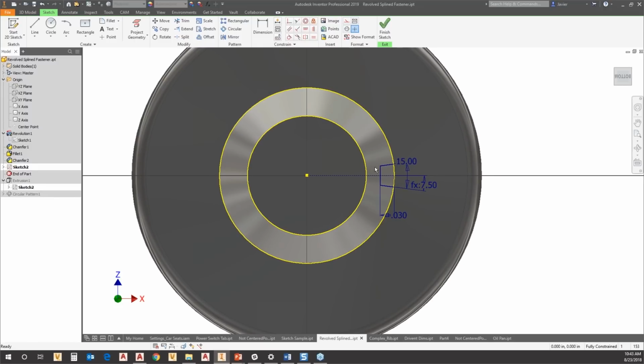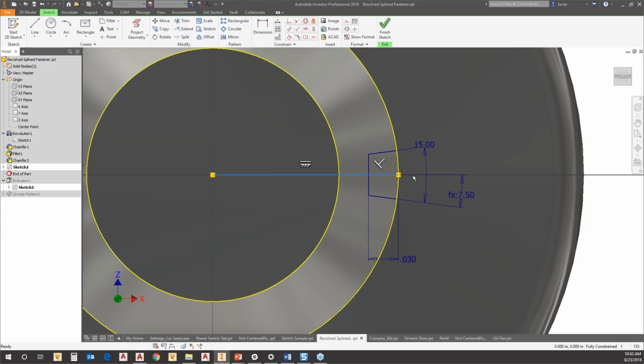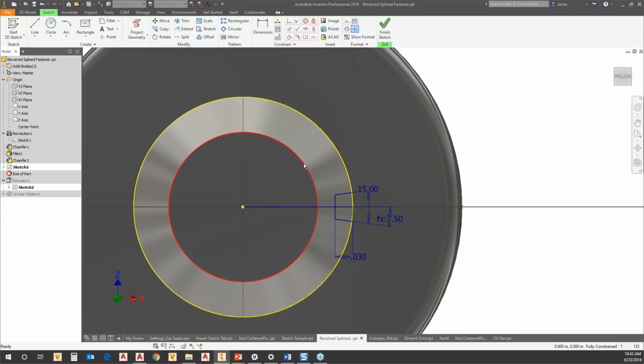Okay, so here, basically I want to create an extrusion. I've got a sketch here, and there's some geometry that shows up here. I use this line to control where this cut is going to show up. Okay, it's just a regular line. I dimensioned 7.5 degrees, and then opened this up 15 degrees. I just use this as a reference. Now, it's only there for reference purposes. Same thing with some of this other line work here, this yellow geometry. And yet, I want to use it to cut geometry in an extrude function.